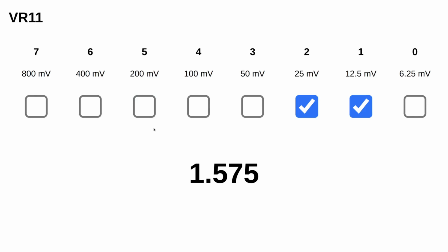Now, if it's at idle, it's probably fine in practice. The current will be low enough, and these voltages aren't that high that you really have to worry about oxide breakdown. But you have to sometimes keep in mind when you're doing transitions like this about the order that you flip the switches in order to avoid your intermediate values from being really high.